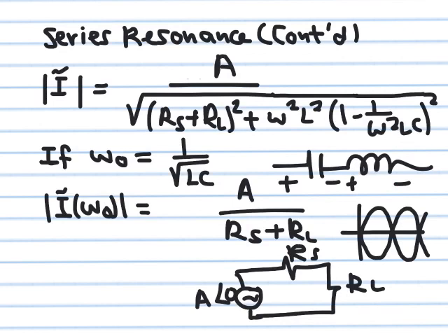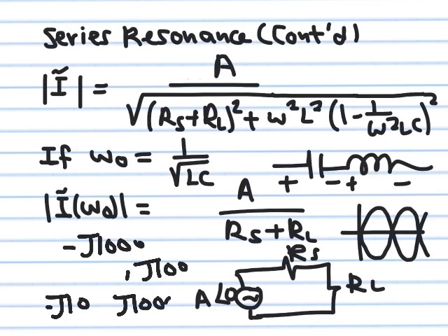So for example, I can give you some numbers here. At low frequency, the impedance of a capacitor may become something like minus j1000, and the inductor, say, is j100. Okay, these can be significant numbers. At very high frequency, the capacitor can be minus j10 and the inductor can be j10,000, and so on. So away from resonance, they are different from one another, but only at resonance do these two impedances become equal, and as a result, their voltages cancel each other out perfectly in the time domain and in the frequency domain.